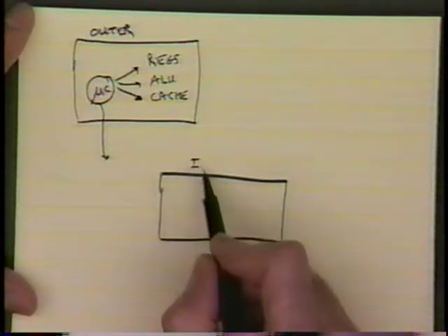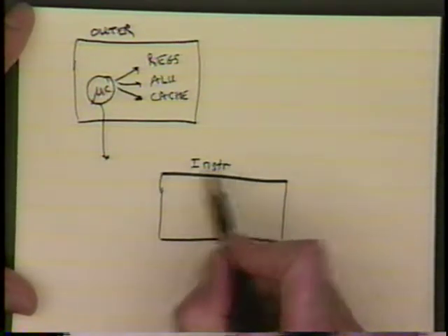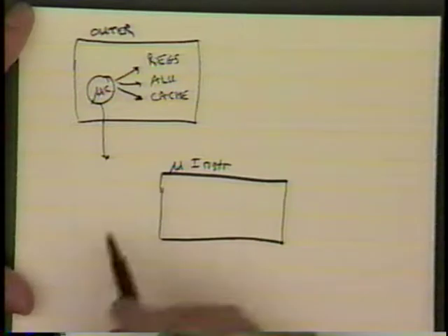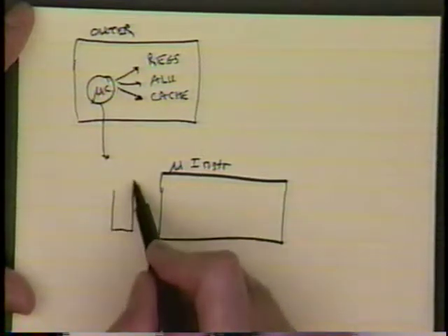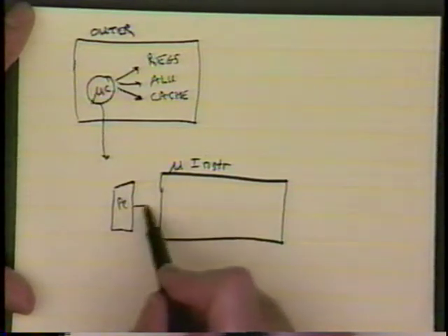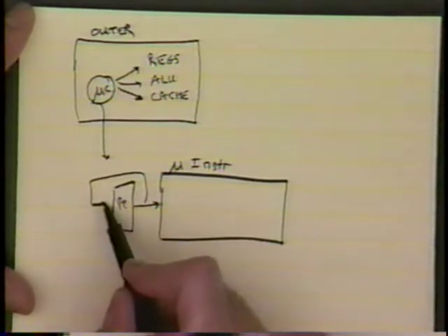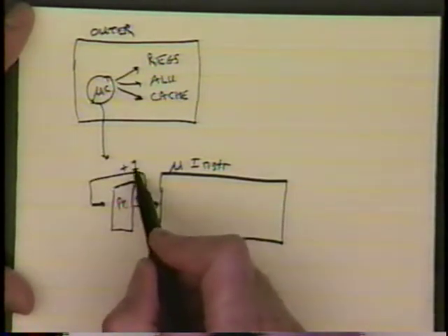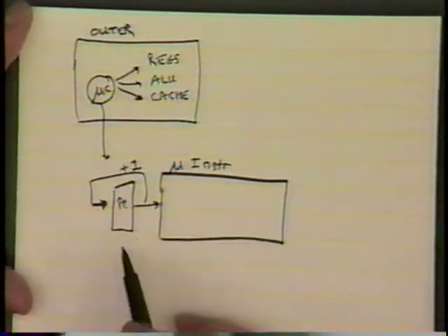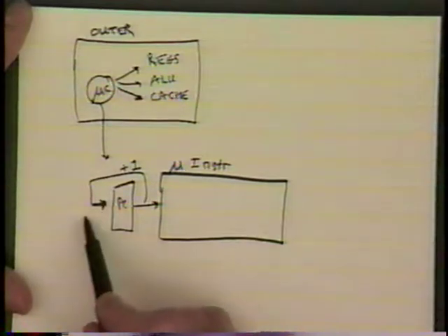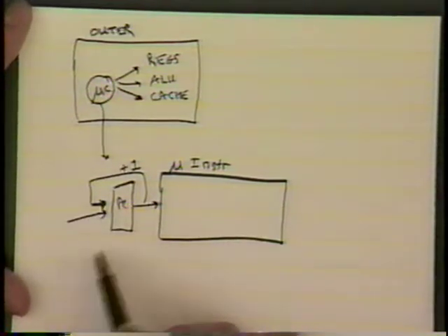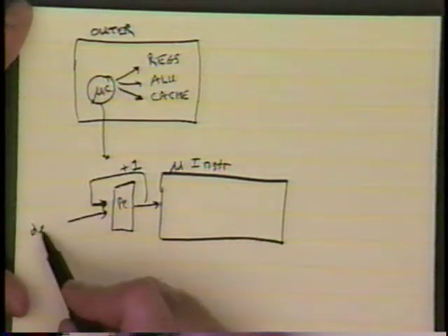This is the instruction memory or micro instruction memory for that computer. It would typically have a standard kind of program counter that gets incremented by 1. It may also have other ways of specifying the location within this micro instruction memory, like a decode table.